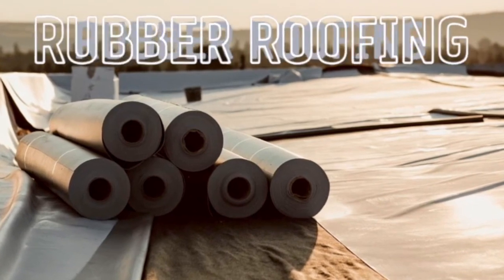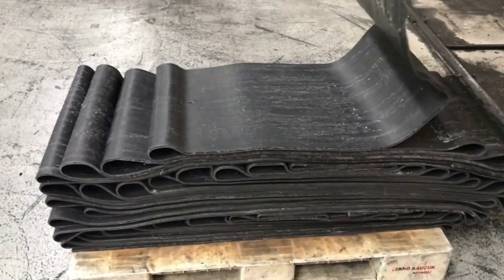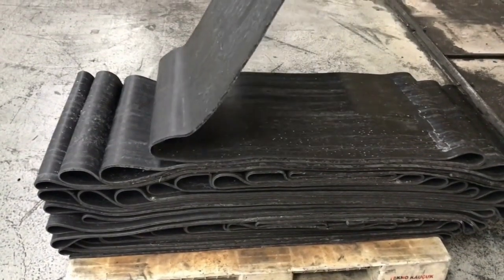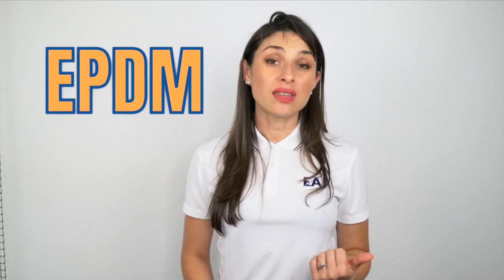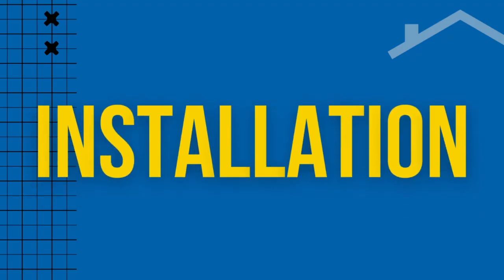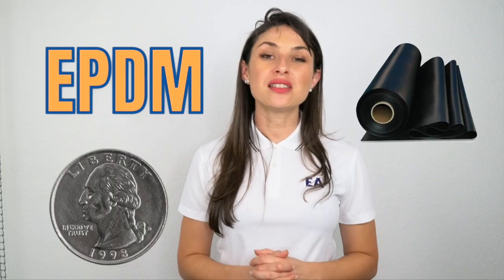This is because it's a single ply membrane material that is flexible like a synthetic rubber compound. EPDM roofing has a darker membrane and this means it will absorb the heat, unlike TPO that will deflect it. Installation. EPDM comes in 45, 60, and 90 thousandths of an inch. The industry standard though is 60 thickness, which is about the size of a quarter coin.